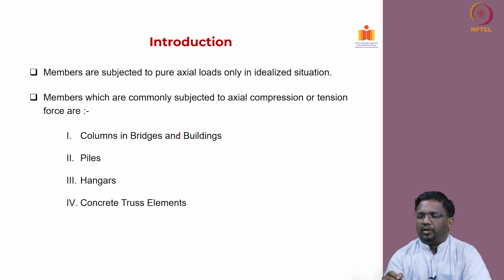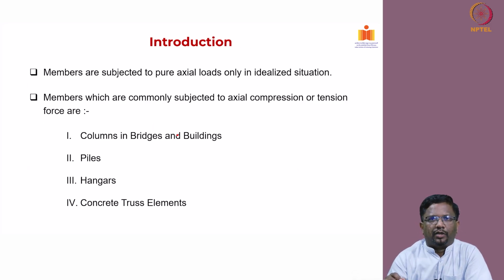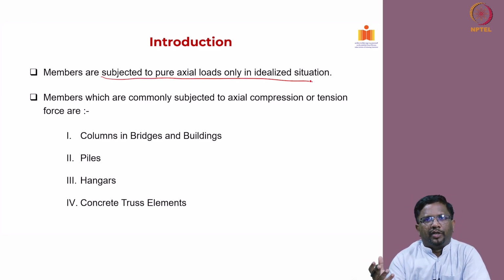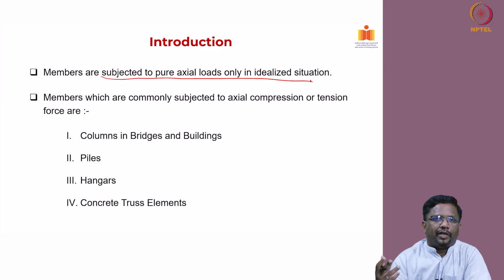So, concrete members or prestress concrete members are subjected to pure axial loads only in an idealized condition. What is the meaning of that? They are always subjected to some bending or shear along with some axial forces. So, it is an idealization.